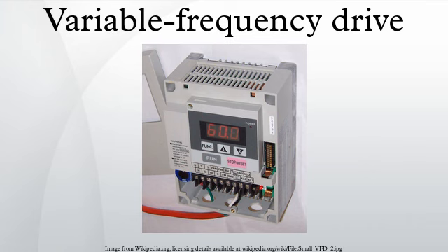An embedded microprocessor governs the overall operation of the VFD controller. Basic programming of the microprocessor is provided as user-inaccessible firmware. User programming of display, variable and function block parameters is provided to control, protect and monitor the VFD, motor and driven equipment.